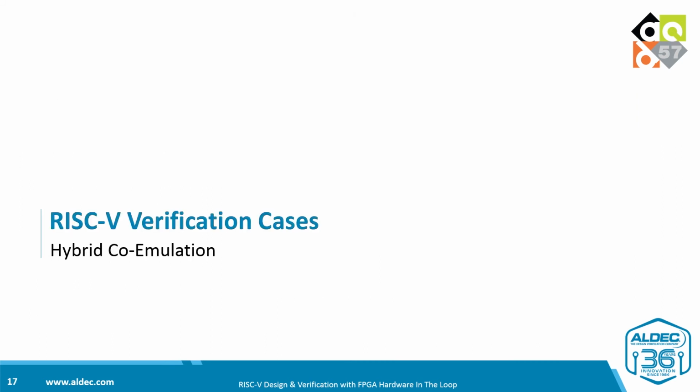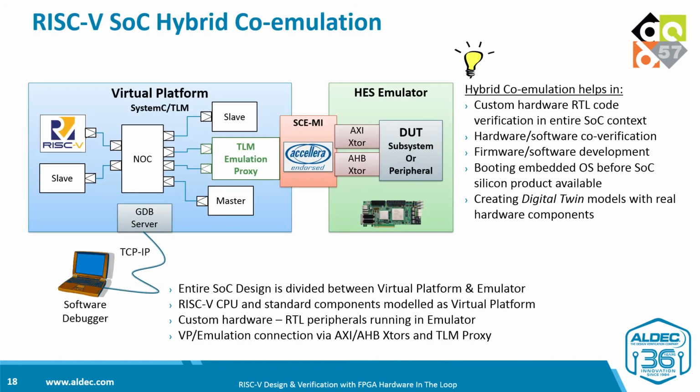Now let's review hybrid co-emulation case. Let's start with defining a hybrid co-emulation term. Hybrid co-emulation is a mixed hardware-software emulation approach where part of the SoC is modeled as a virtual platform, and some other parts or subsystems are running in the FPGA emulation board.